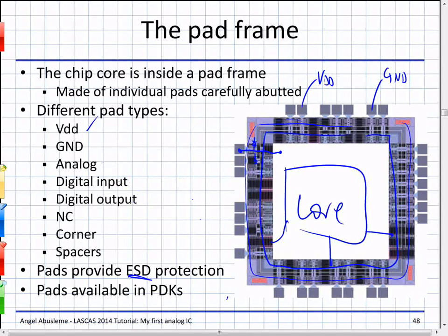We have digital input paths that have buffers, so you have something like this. This is a digital input path with protections too. We have digital output paths, which is the same thing, but the other way around. It has buffers. So you come here with a very, very small gate, and you can drive here a TTL circuit.